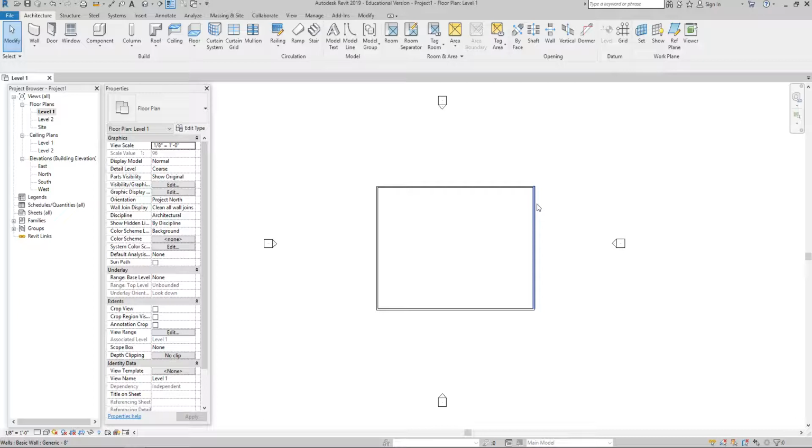You'll see that workflow in drawing, and in the creation and definition of a lot of things. One thing you're going to notice when we start creating wall types is that there's no new wall type button. You take an old wall type, redefine it, and create a copy, and that's how you create a new wall type. So you're constantly revising things, and I've gotten used to it. It is what it is.